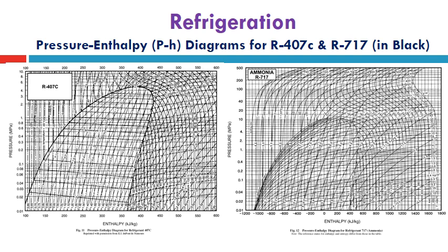The vertical axes of pressures in megapascal and the horizontal axes of enthalpies in kilojoule per kilogram are shown with their values, which are needed to solve the cycle corners, in case of using R407C in some problems, or R717 in other problems.